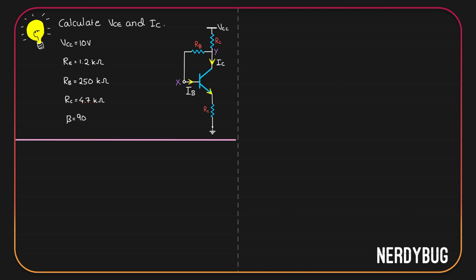is 90. Let us start by applying KVL in the base emitter loop. I mean this one. We reach the emitter, we go to the base, we go through RB and then RC to VCC, which is just a cell that goes back to the ground. I'll start from VCC. Current through RC is IC, so a potential drop of ICRC will be there. I have to write minus ICRC. As I go on, I have RB here. Current through it is IB. So IBRB will be dropped across RB. I have to write minus IBRB.